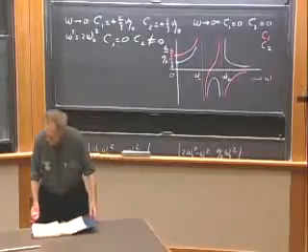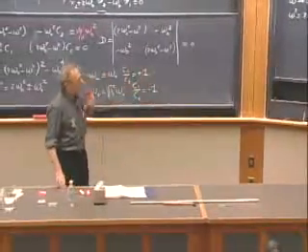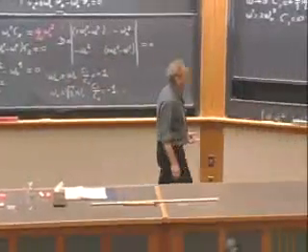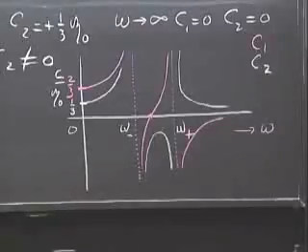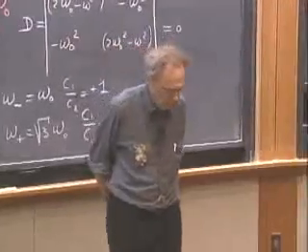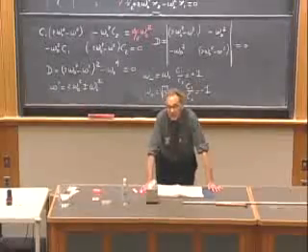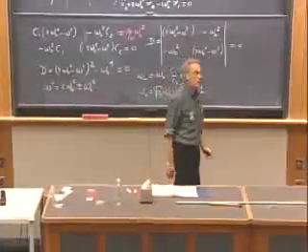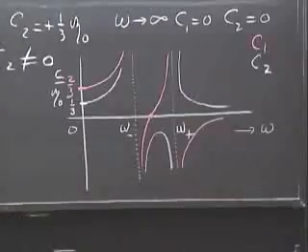Now we ignore damping, and because we ignore damping, we get these unphysical infinities when you hit the frequencies omega minus and omega plus, these resonance frequencies. Now if you include damping, then the solutions become extremely complicated, but of course you avoid the infinity values, but the resonance amplitude can still be very high. And so these plots are still very useful, provided that you don't interpret the infinities as being real, but something that is very large. If Q is high, then of course the amplitudes are enormously high. And this can lead to destruction.